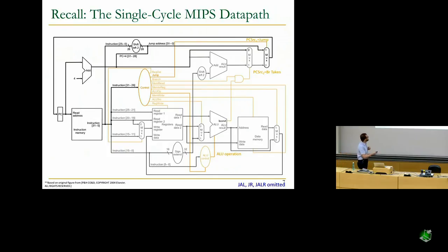What is the combinational logic that you need to do the updates of the architectural state? You see the state elements inside here, but you also see a bunch of data path elements like muxes, the ALU, the address calculation adder over here, and a bunch of shifting logic, sign extension logic to implement the instructions. And if you recall, in the last lecture, we went through almost every single instruction that is important to us in this course and derived this data path. This is the result of the last lecture, okay?